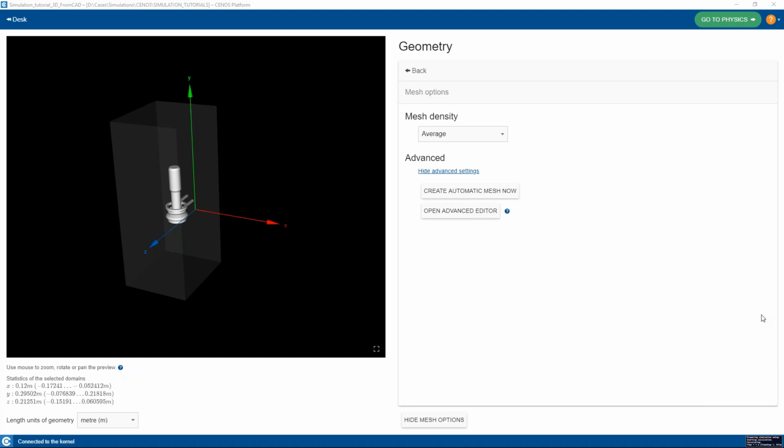So, one thing that would be very cool is that when you start the modeling, at time increment number one, it calculates the temperature, and let's say the temperature is 500. But I set the temperature goal to be 800. So it plays with the current or frequency to reach that temperature, and at the end it gives me the profile of frequency or current with which I can reach 800 inside my complex part. You get it?